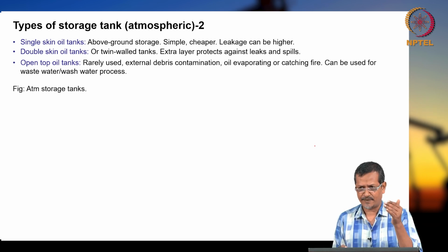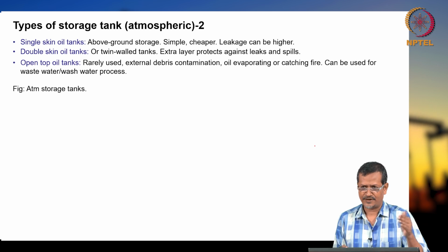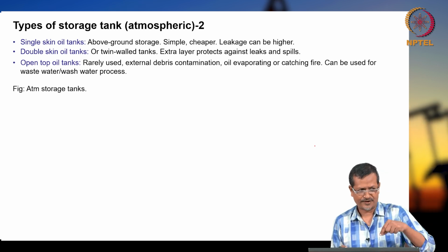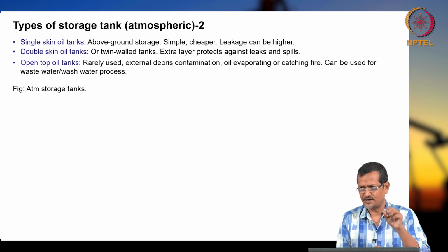But if you have blanket gas, in that case you are maintaining pressure, okay. So, you are not allowing outside oxygen to enter into the system. You are forcefully keeping the inside pressure a little bit higher.